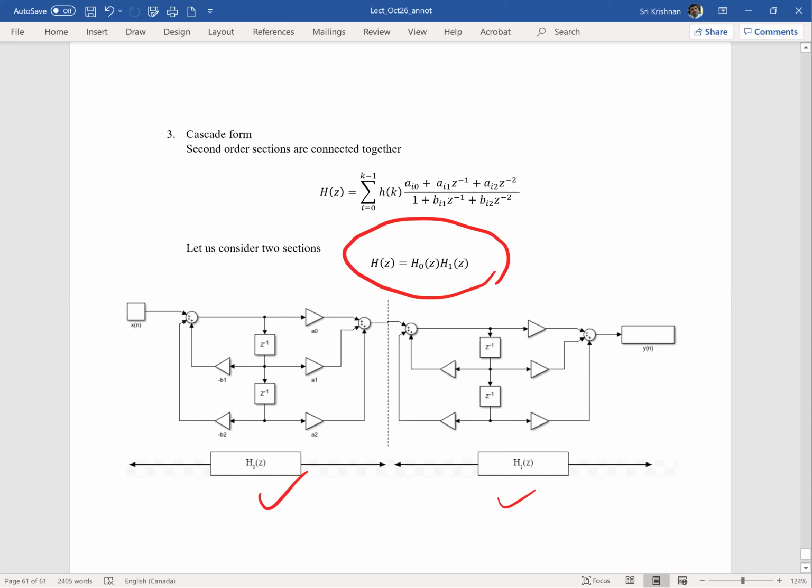So in this cascading operation, we can probably incorporate parallelism. In the first case, I would be working on H0(z). In parallel, I could also work on H1(z). And given that pretty much all processors we are dealing with these days have parallel mechanisms, this modular approach helps us fast track the process. So it increases the efficiency and the speed by reducing the latency in the system, the cascade filter.